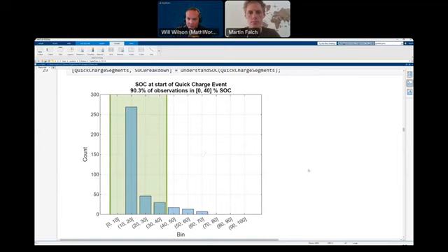One other thing I like to do, maybe by way of curiosity, is understand, when we go into these quick charge events, what is the state of charge? I want to understand from a statistical perspective what sort of trends or behaviors we are seeing. And what we see is about 90% of the time we're between 10 and 40% SOC. The reason being, if we had a whole wide variation here, we maybe would have to have multiple models. We're not going to just assume there's one model for everything. Maybe we need to understand this. So we're going to use just this 90% of observations band to further our calculations.